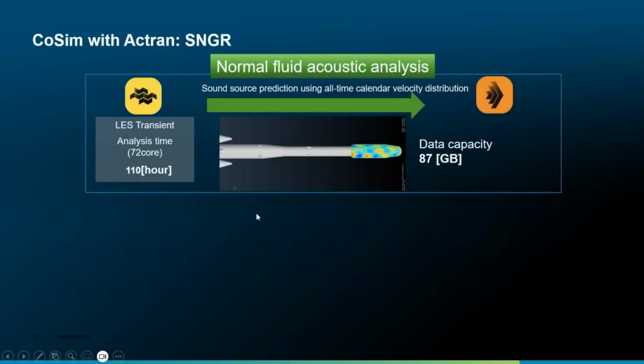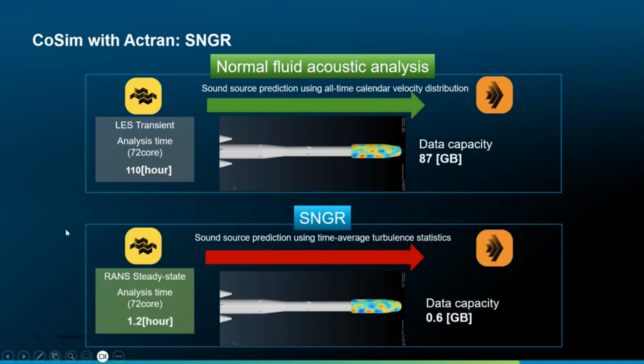As I said, we perform a CFD simulation to get the initial boundary condition to be processed in the acoustic simulation. Traditionally speaking, we need a very detailed CFD run to be able to make this kind of coupling. When I say very detailed, we are talking about large eddy simulation, CFD simulation. So it's something quite heavy in terms of calculation time, and calculation file size as well. And here, the fact of working closely with acoustic teams, because we are in the team at MSC, so our developers can freely talk to each other.